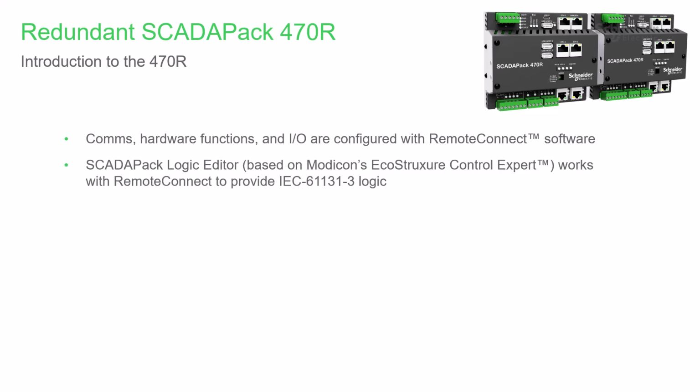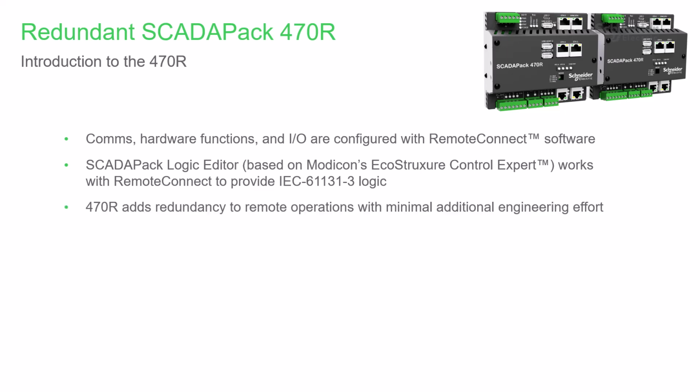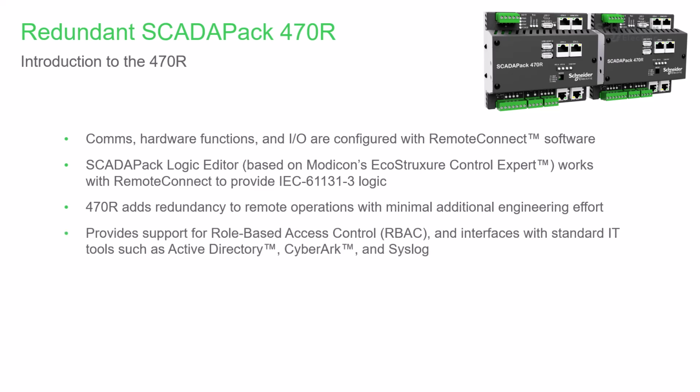the SCADAPack Logic Editor, based on Modicon's Control Expert, works with Remote Connect to provide IEC 61131-3 logic programming capability. The 470R adds redundancy to remote operations with minimal additional engineering effort. This will be explored in more detail later. Support is provided for Role-Based Access Control, or RBAC, and the 470R interfaces with standard IT tools such as Active Directory, CyberArk, and Syslog. Configurable web server functionality is included as well.